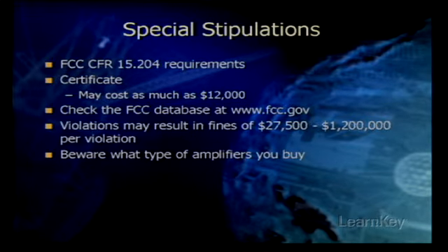And some amplifiers will cause the FCC to only certify the system as being able to use particular channels, such as the DSSS channels 2 through 10 or 3 through 9 instead of 1 through 11, like an unamplified system can. This is due to how the RF signal is amplified and bleeds over into the licensed radio frequency spectrum outside of the ISM or UNII bands.